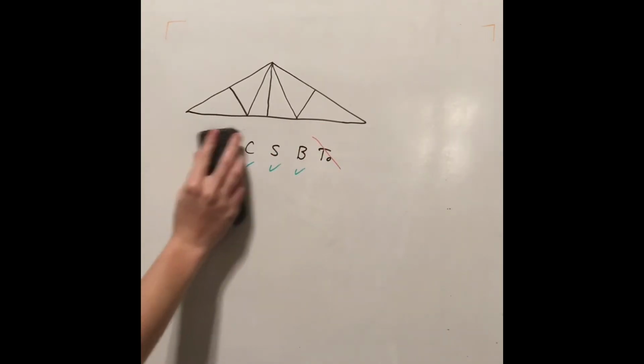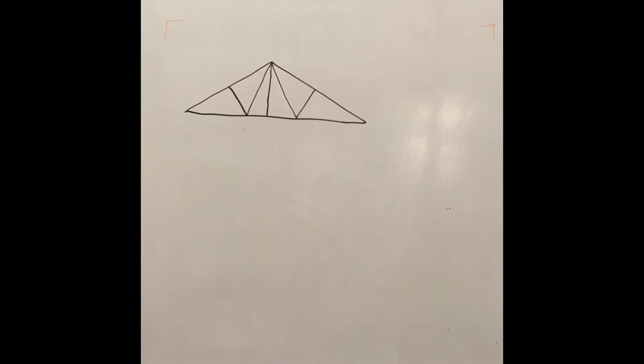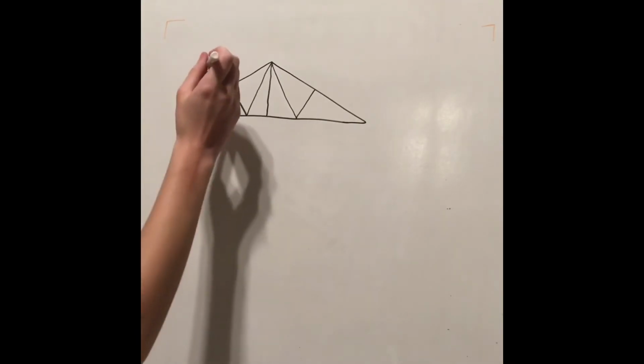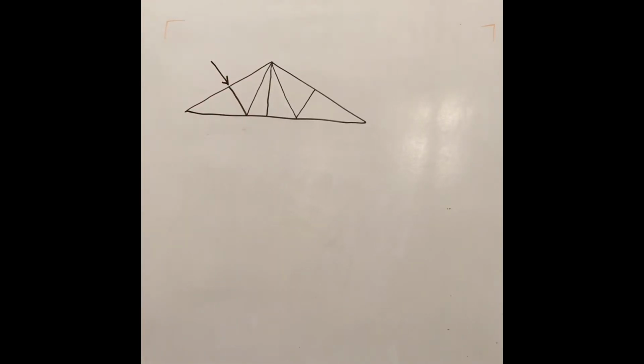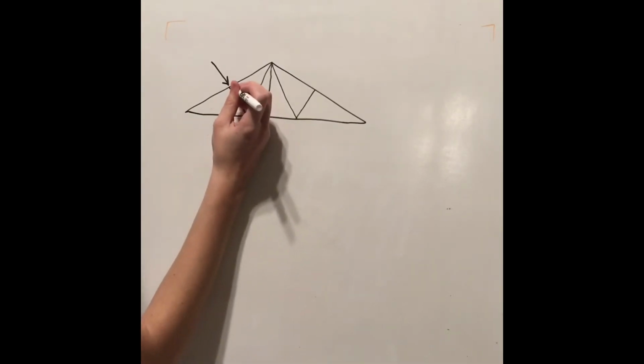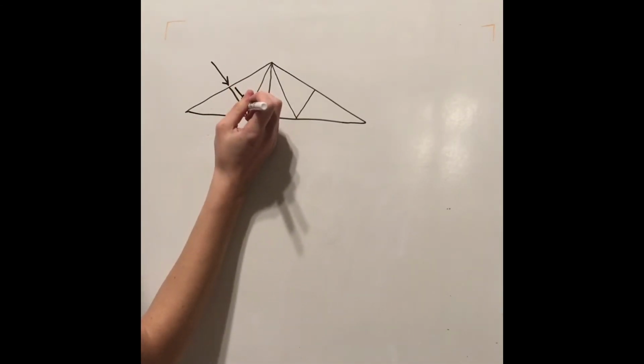Torsion is not present in this system. Bending force from gravity occurs on the top beam due to its long length. To counteract this force, another beam is placed underneath it so it bisects the top beam at a 90-degree angle, causing most or all of the bending force to be transferred into the middle beam, which then gets compressed.